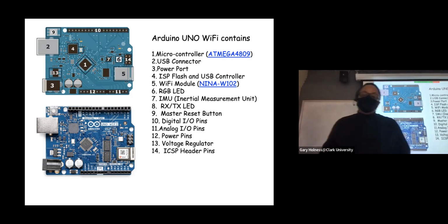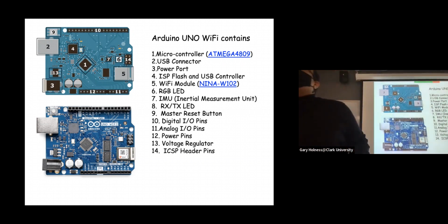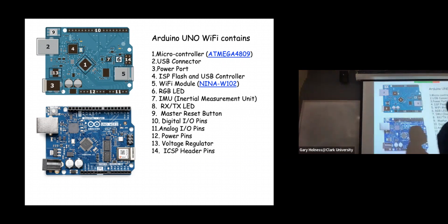has some voltage shaping called a voltage regulator. That's for giving you stable power. Now, it's really important for digital systems to have stable power, because if you were to measure even direct current going into such a board, well, it's going to flicker a little bit. And one of the issues you have with digital circuits is that you need stable current, because if that current drops a little bit below what it should be, the board's just going to shut off. And so you need something called a power regulator that takes the actual voltage and makes it much more smooth signal. And we're going to talk a little bit more about that in a future module.